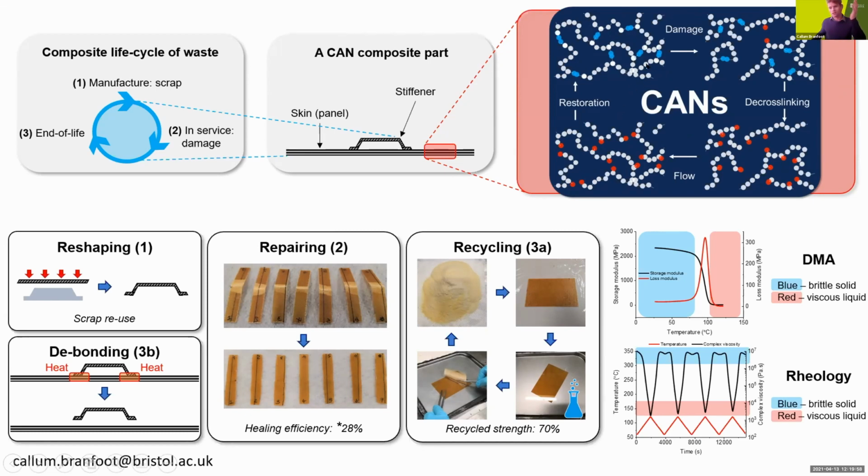And what these are essentially is a type of polymer that lies somewhere between the two main classes of polymer, thermosets and thermoplastics. So in this diagram here, the white circles represent the polymer backbone, and the blue circles binding them together are the crosslinks. So structurally, they're similar to thermosets, but the difference is these crosslinks contain a reversible chemistry that, when activated, allows them to decrosslink or depolymerize as well.